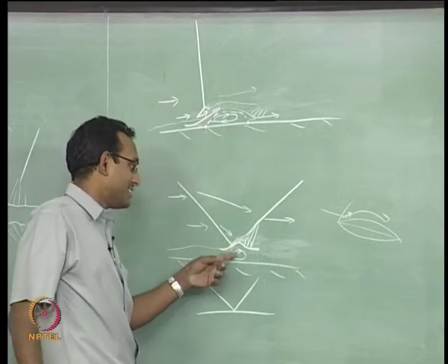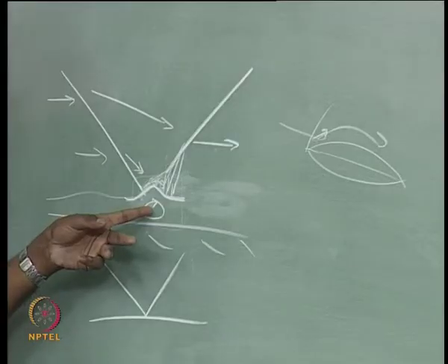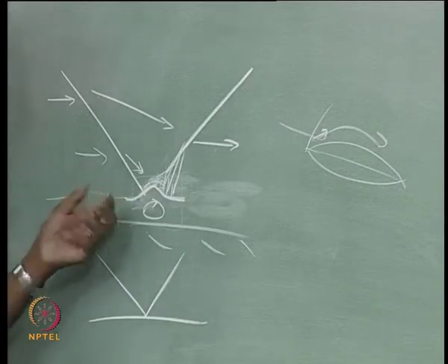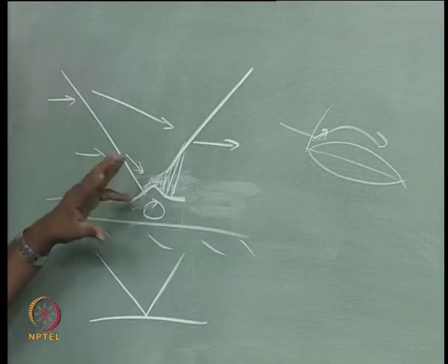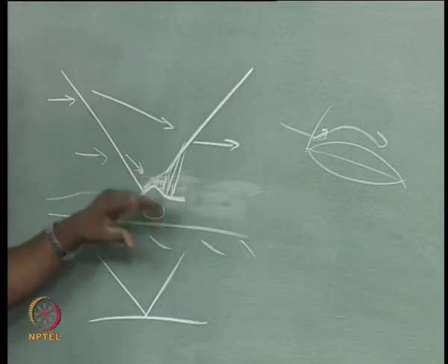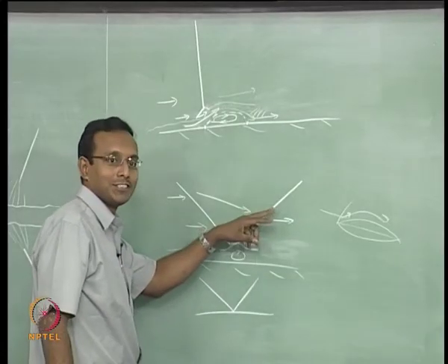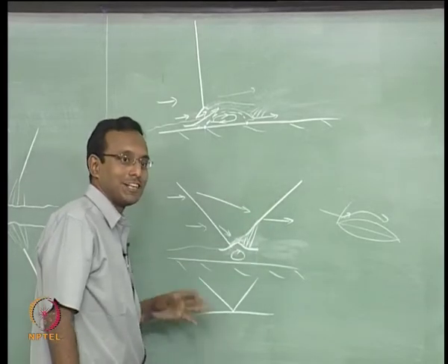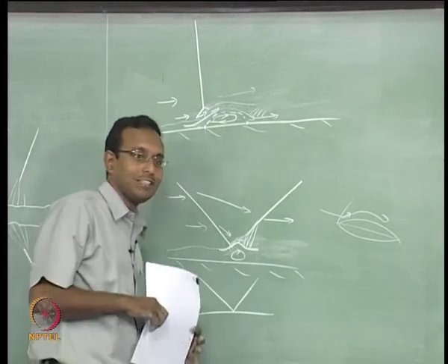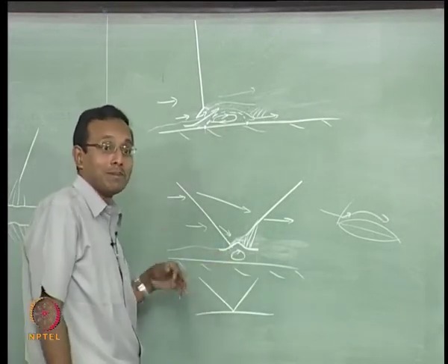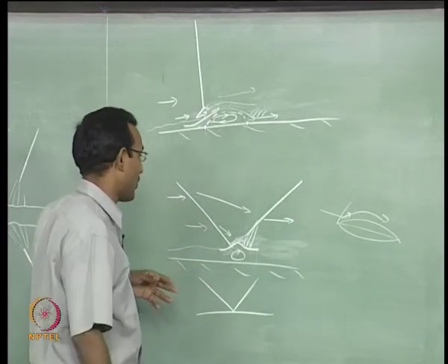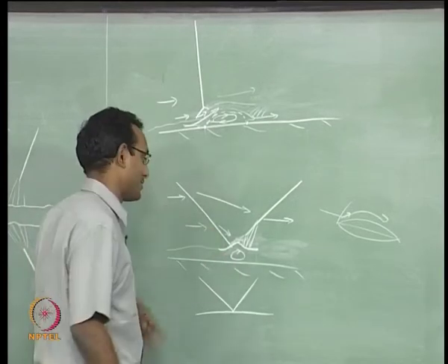Typically in supersonic intakes, this is a serious problem, because now this recirculation can cause eddy shedding and unsteady flows. This will start to increase and decrease in size. When that happens, this shock is going to oscillate up and down, because the size of this body is changing. Okay. So this is going to respond to it unsteadily. When that happens, you are going to have unsteadiness in your flow field itself. That is going to cause a lot of trouble. This is one reason for having intake buzz, the way they call it in supersonic combustion ramjets. One reason for it, not all the reasons, this is just one of the reasons possible.